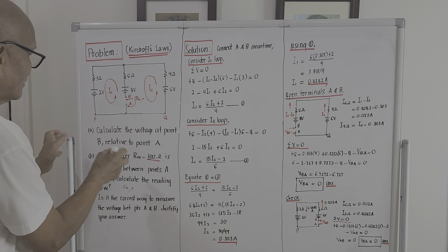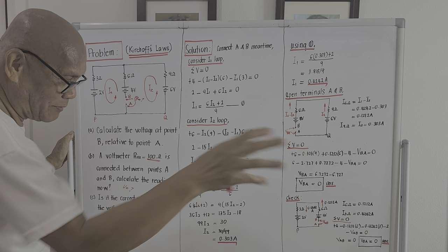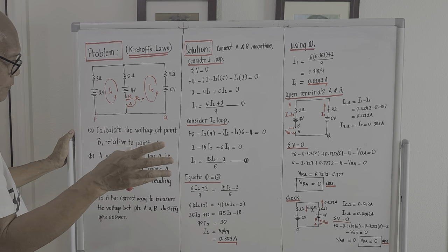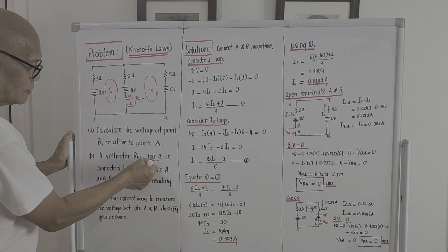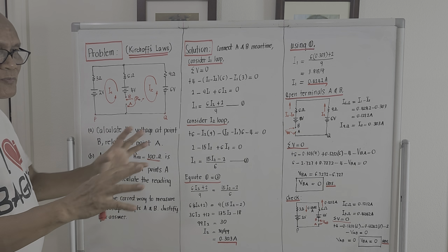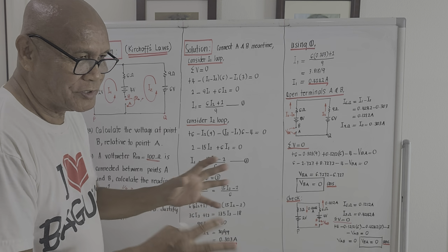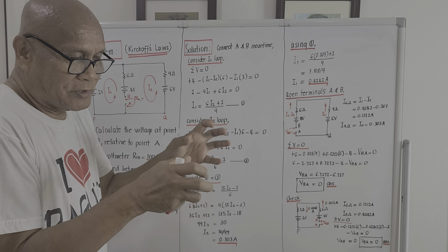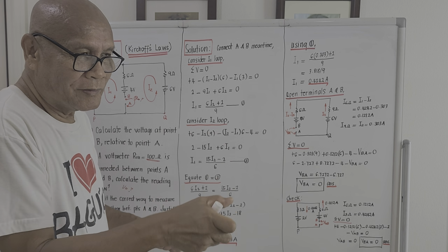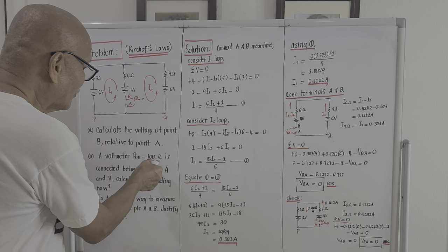Before I present the voltage across B, because I will be presenting two solutions, the solutions are actually the same. I will answer letter B. Mr. Werakudi placed a voltmeter here with an internal resistance of 100 ohms, and he is asking what will be the reading. There is a problem here because it seems he doesn't know the specification of multitesters. Multitesters are designed so that the internal resistance should have no effect on the reading. And the value he had given me, 100 ohms, is wrong.